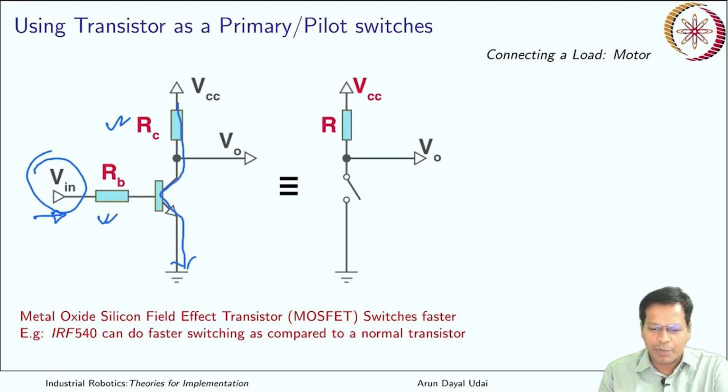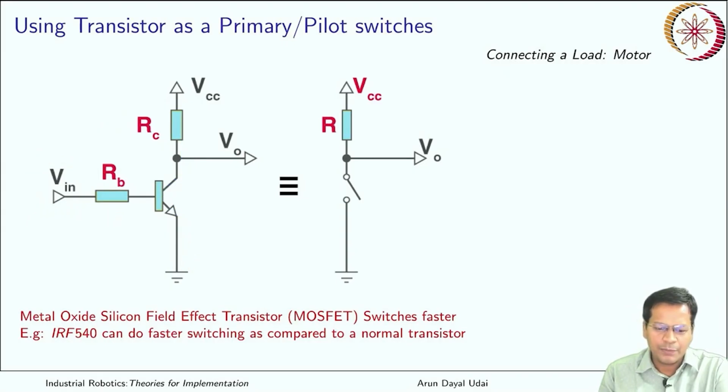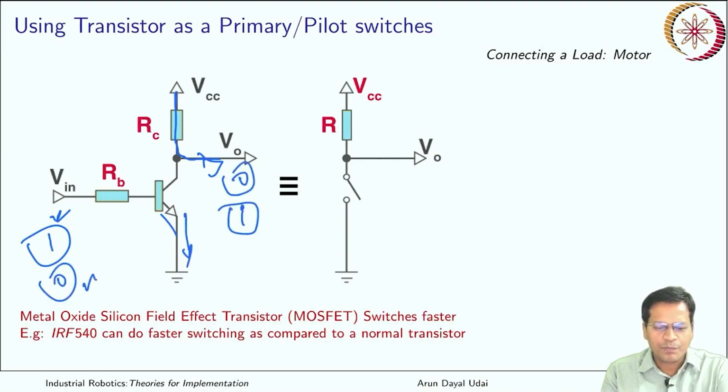Okay, so that is the gate type of operation, right? If you don't apply current from here, so if no current is there from here, current will not flow through this transistor, and finally it will go all from this direction. So it is just like a NOT gate. If you provide 1 over here, you see 0 over here. If you provide 0 here, you see 1 here. If you provide 1 here, you see 0 here. So this is just a NOT gate operation.